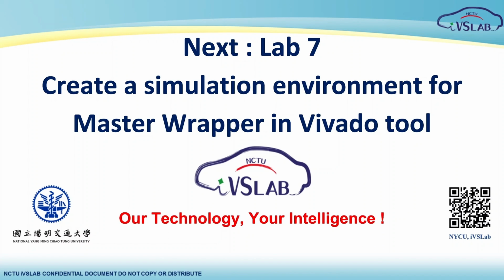Looking ahead to our next lesson, the primary goal of Lab 7 is to build a lean, efficient verification environment. You will learn how to test our custom master wrapper directly via a test bench without depending on the Zynq processor core. We will utilize an AXI connector along with a BRAM controller to construct a standalone test bench platform, implementing an automated test cycle that encompasses write, read, and data comparison operations.